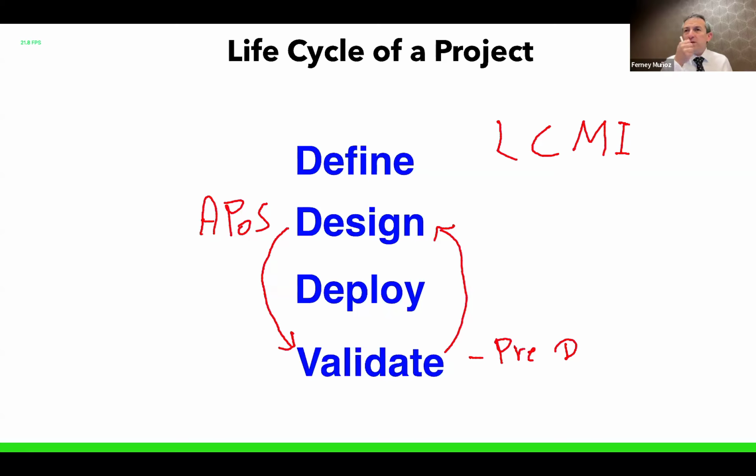So being part of this, making site visits and asking questions, talking to the constructor guys and all that before the deployment, that's great. So once the design is modified, and sometimes it's the opposite. You say 33 APs, and then you go on site and you do surveys, and they say, like, man, this AP that originally I thought was going to cover the reception and the restaurant and the waiting area also covers the gym and the exit to the parking lot.